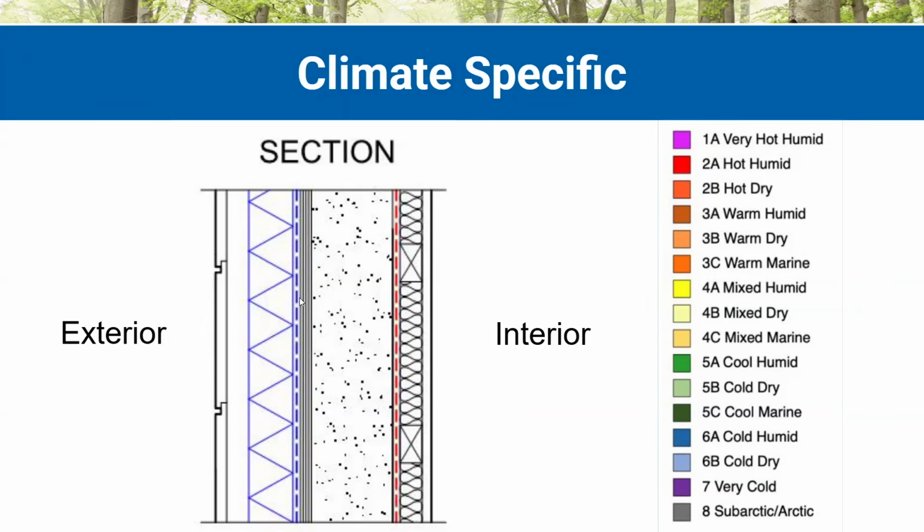Climate zone 6 is oftentimes where I'm seeing projects do sheathingless assemblies, where they're using diagonal strapping or let-in bracing instead of a plywood or OSB sheathing, because they don't want the vapor retarding qualities of that plywood or OSB. Maybe they're switching to a masonry sheathing, like a dense glass element that has a higher vapor permeability. Some other climates might be doing that for their fire ratings.